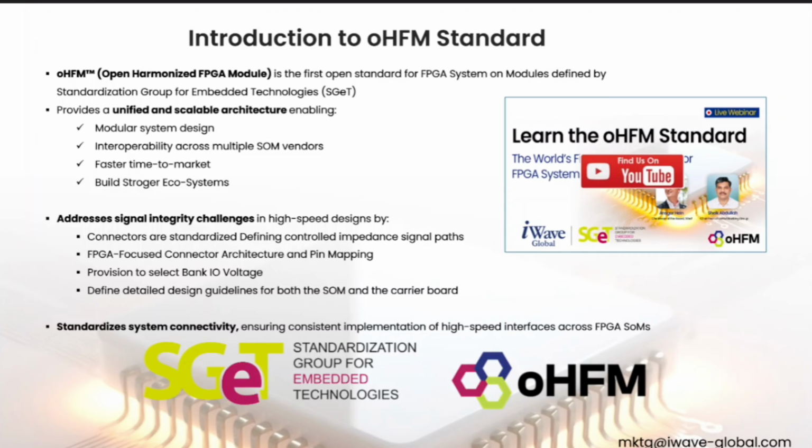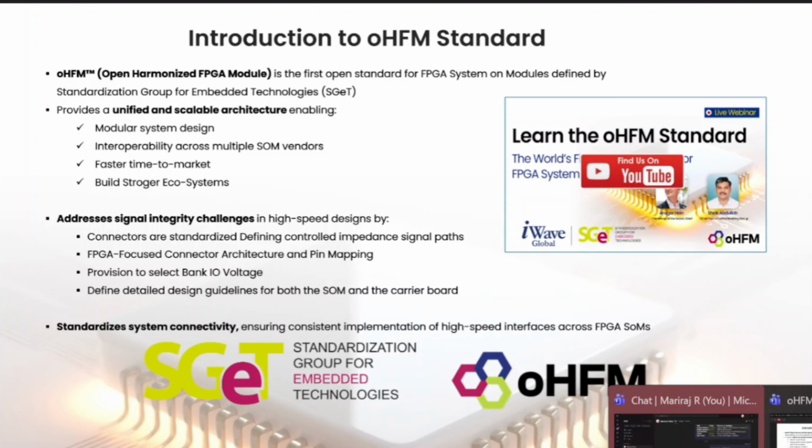During the connector selection process for oHFM, the Samtec team worked closely with the ecosystem partners to ensure the connector interface and signal paths were optimized for next generation high-speed requirements. The connector pinout was defined in collaboration with the different SoC vendors, also considering the demand for different IO bank voltages, to enable variable IO configuration from the baseboard while defining the pin mapping and the pinout for the standard.